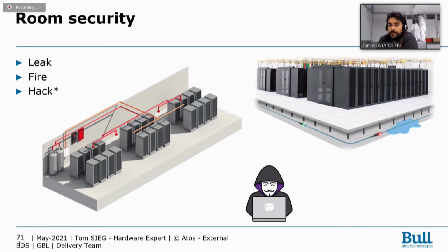If you are on a direct cooling solution, the leak could be into a compute blade, or into the rack itself. In this case, the glycol will be able to damage some components and cause a short circuit on the electric components. So you will have damage on one rack component, or into the rack itself, many components.